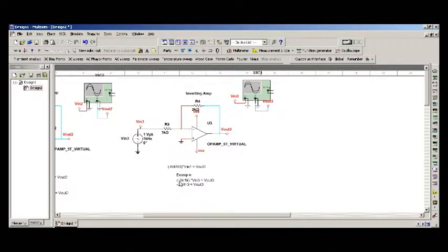And then we have our negative in front. Negative 2 times Vn should equal V out that we have here on this oscilloscope. And so what we expect to see is an inverted version of Vn scaled up by 2 to be V out.